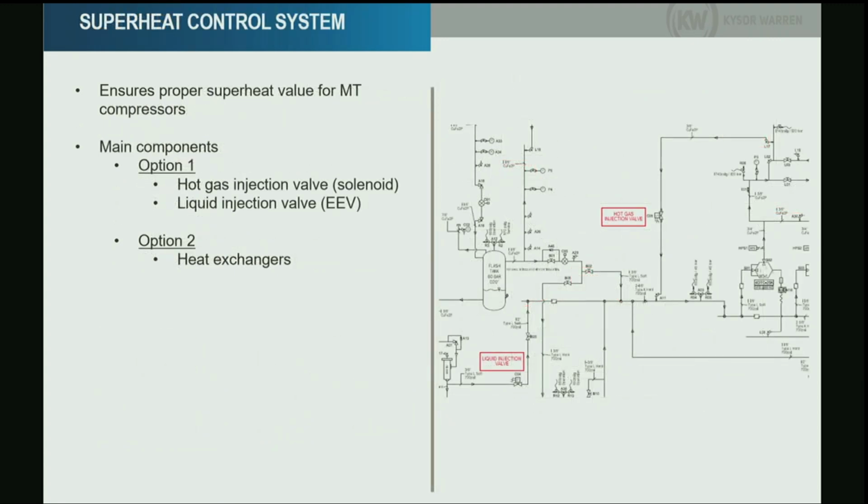Ignacio, I have a question. Yes. You guys make cases as well. Are you guys seeing aluminum coils on CO2 cases? No, we don't use aluminum for the coils. The serpentine is copper, the aluminum fins only, but I know there is a manufacturer with aluminum coils. We're having a bunch of leaks. They're the only ones that we're seeing leaks on, aluminum coils returned under warranty already. Oh, really? Yeah, no, we don't use aluminum for that. Thank you.